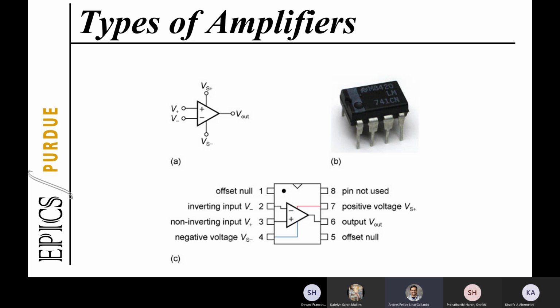We see there is a dot, the grayish band on the left side and a dot right there. That dot is the same dot that is right next to pin number 1 in the diagram at the bottom. If you ever look at the diagram, there is always going to be a dot that indicates which one is your pin 1.